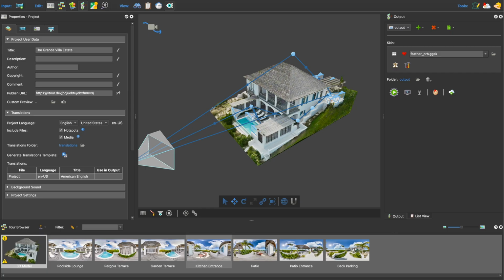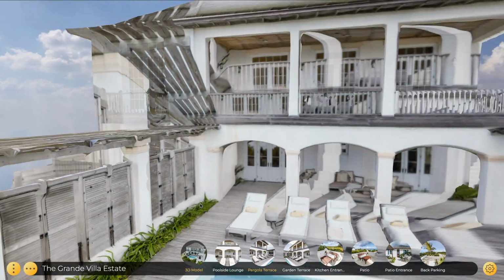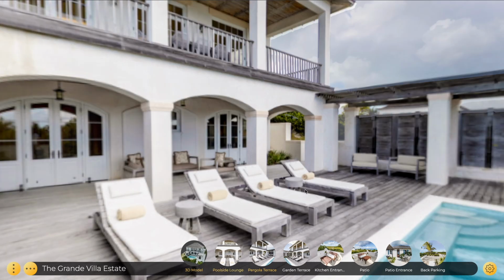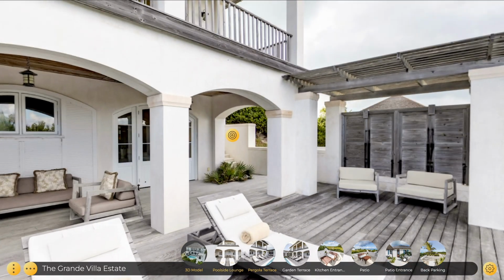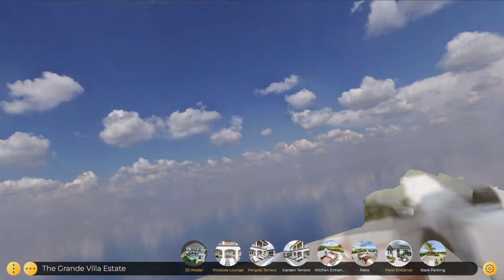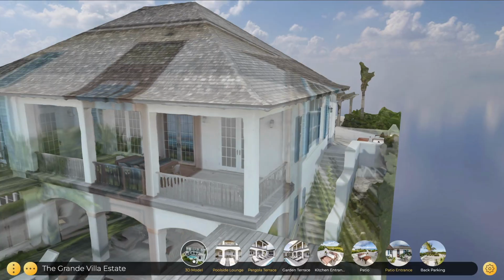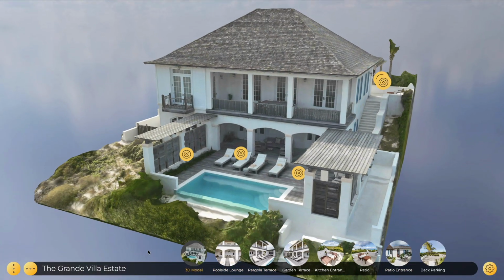Cluster points group camera points that should share the same routes without affecting the camera path themselves. The default view camera point lets you define routes between the 3D model node and the panoramas in the tour. Together, these tools help create smooth transitions that avoid passing through the 3D model.